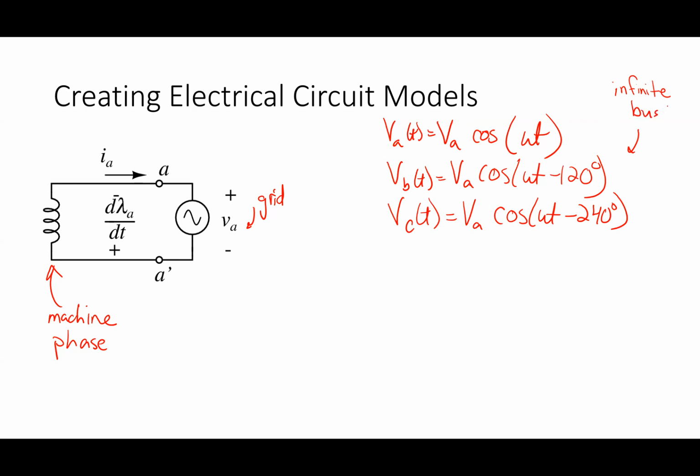What did I say that meant, an infinite bus? Just your voltage source, a voltage source that is infinite, or sometimes we'll say stiff bus, stiff or infinite bus. The term stiff probably makes a little bit more sense because the way I think about a bus is a voltage source. So if I think about any bus, looking into there, I have a voltage source, I have a line where the voltage should be constant. For it to be, quote, stiff, what do you think that means?